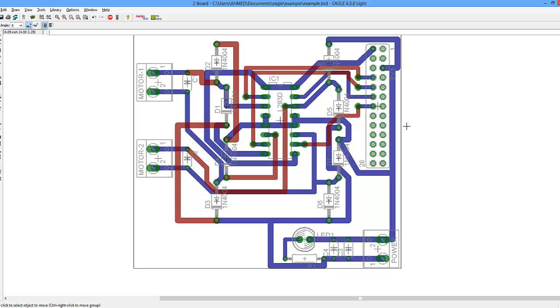Now this worked out fine because most of the pins that I used for the Raspberry Pi are on the left side, not on the right side, in my design. If you are also using pins on the Raspberry Pi's right side, then it's not a good idea to place the header here. So probably you would put the header in the center of the design or a little bit inside the design, so you can solder the wires on the right or take wires from the right.